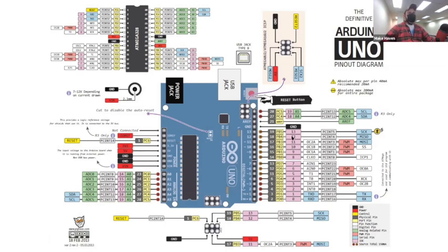But this is a map for how it actually interacts with the world. And it's a lot to take in. You can't learn it all at once. But if you wanted to, here's the pin for the actual chip. Basically, these completely mimic this. They're just mapped through traces and wires embedded into the circuit board. So they come out in this format that's standard across all Arduinos.